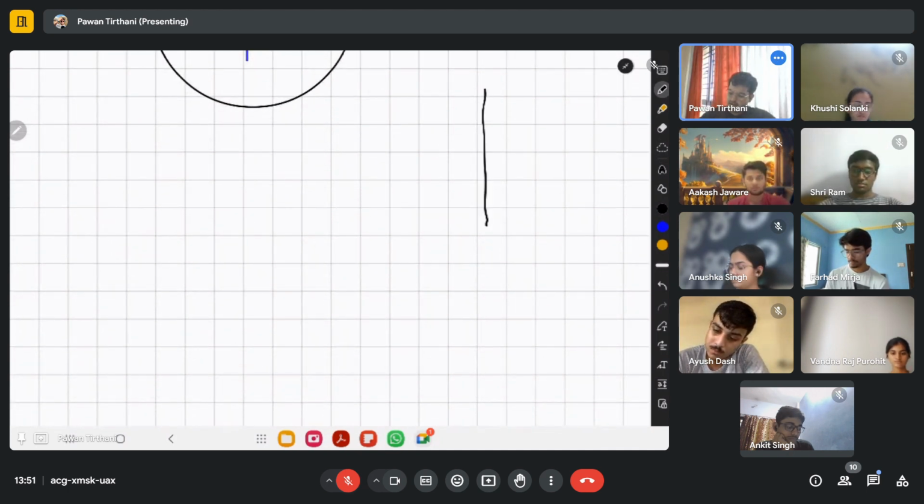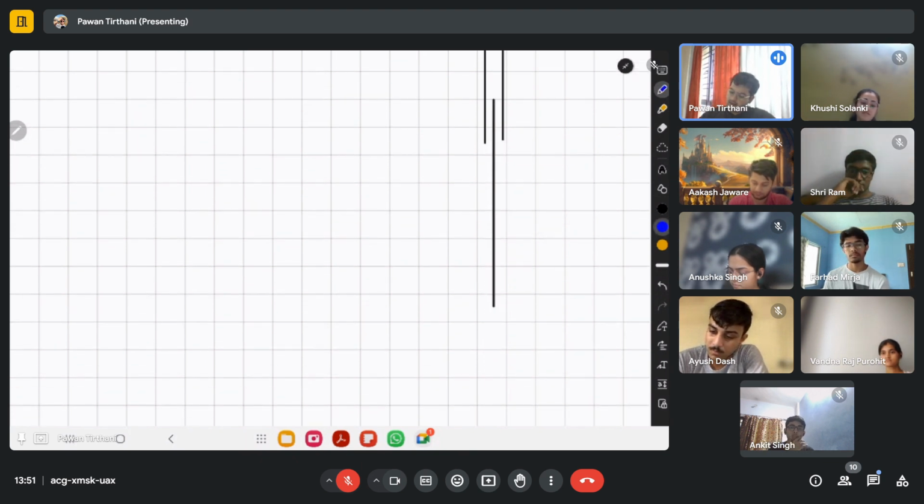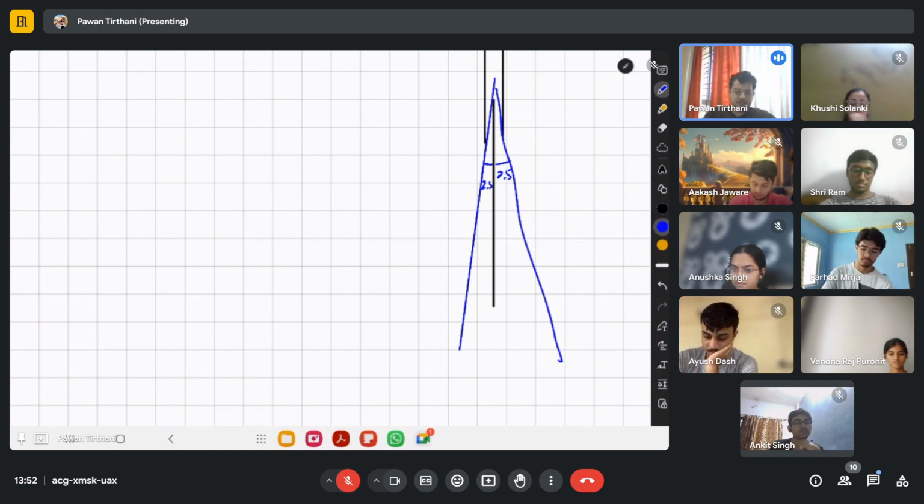That means if this is the runway and this is the extended runway center line, I have to be just 2.5 degrees left or right, and I will be on the edge of the CDI. It is so sensitive. So can I say that the localizer is more sensitive and more accurate as a navigation aid? The answer is yes. Any doubts?